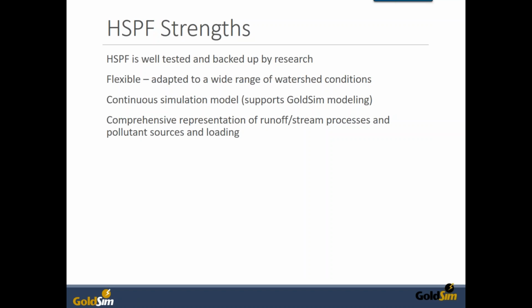It is comprehensive in its representation of the runoff and stream processes, and also for pollutant sources and loading, but the part that is included in GoldSim right now only includes the runoff for pervious catchment. And while the whole reason behind HSPF is for pollutant loading and water quality, we have not built that portion into GoldSim at this time, although any of you could do it if you wanted to.